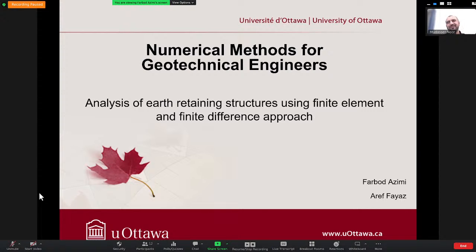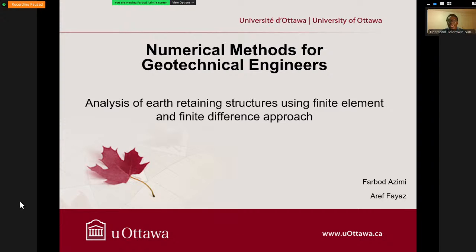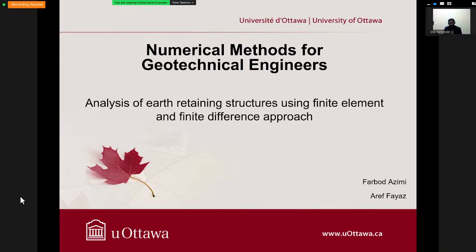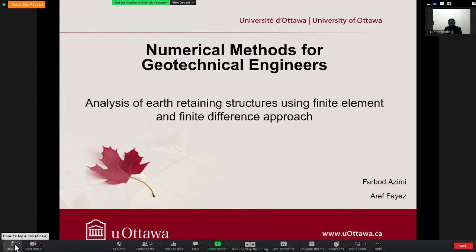Yes. Maybe considering the type of structure and whether it's a long-term or a short-term case. For a long-term scenario, a practitioner would consider going with the finite element analysis, rather than the limit equilibrium method, which maybe is more suitable for short-term analysis. And also the finite element is able to predict vividly the complex structure, unlike the analytical method.